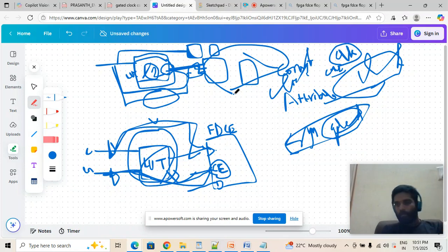This is a rare scenario, but when you do some clock generation and apply the clock gating, just be very careful. You need to modify the constraint. After synthesis, after implementation, you have to modify that constraint. The tool will give you the information from the constraint point of view.